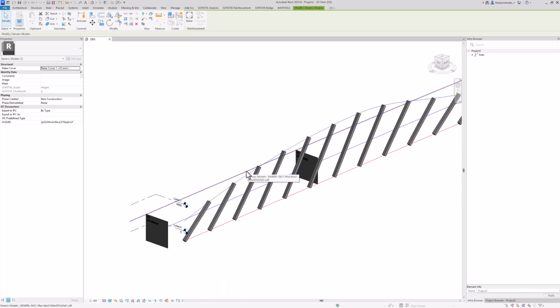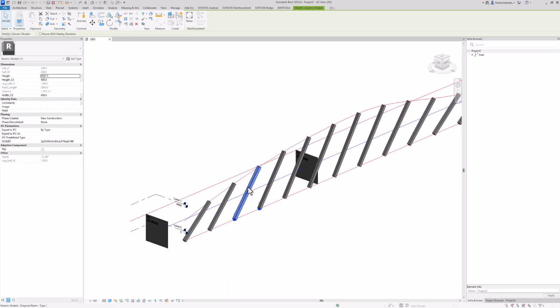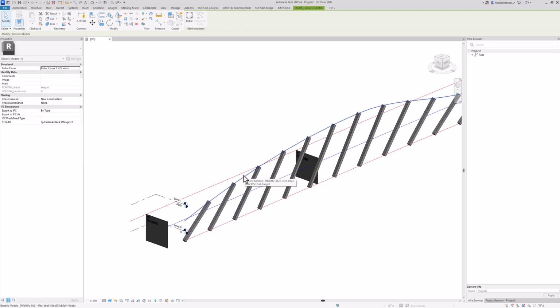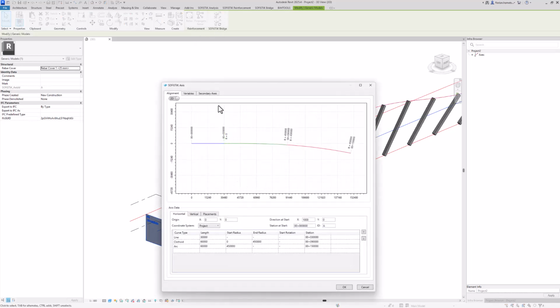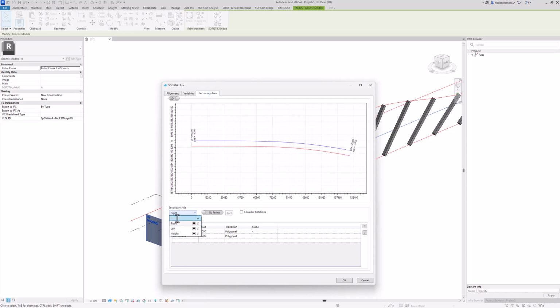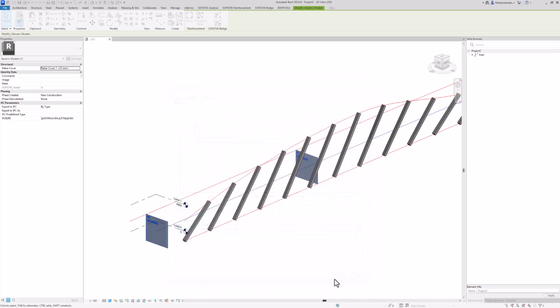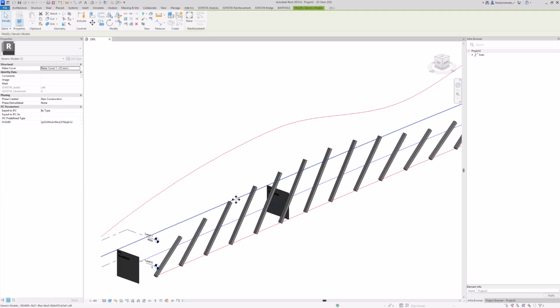Next up, I want to show you how to create this cross member, not depending on a variable, but on a secondary axis directly. To do so, I want you to modify your main axis and move this secondary height axis to the left side. So instead of negative 5,000 to positive 5,000. So here you can now recognize this is going to be our bottom reference and this is going to be our top reference.